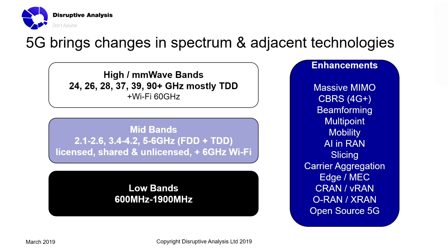On the low band, we can start to expect to see some of the existing lower sub-gigahertz or sub-2 gigahertz bands used for 2G, 3G, 4G being refarmed by some of the carriers for variants of 5G. And they should have better indoor penetration from outside, but they won't be able to support, in most cases, the sort of ultra-reliable low latency services I mentioned before.